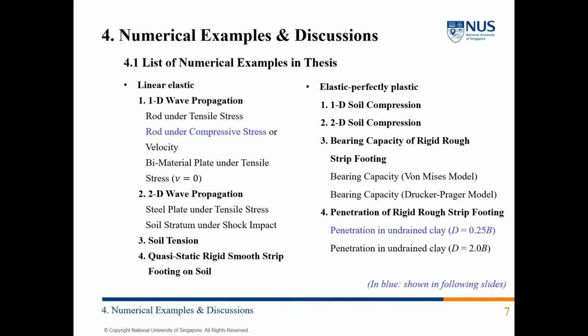To demonstrate the capability of CPM in solving solid mechanics problems, a series of numerical examples are studied, involving linear elastic and elastoplastic problems from small to large deformation. Due to the time limitation, only two representative examples will be shown in the following slides, which are a rod under compressive stress and footing penetration in undrained clay.